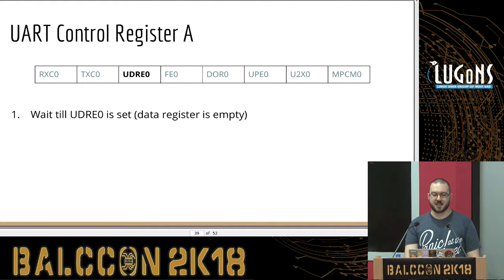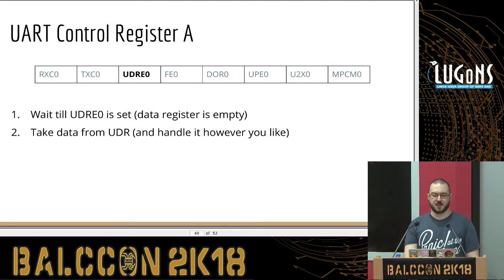So how would we go about sending? We wait till the data register is empty. We write to the data register, and then our emulator goes ahead and takes the value from the data register and does something with it. In my case, I'm just dumping it to standard out.